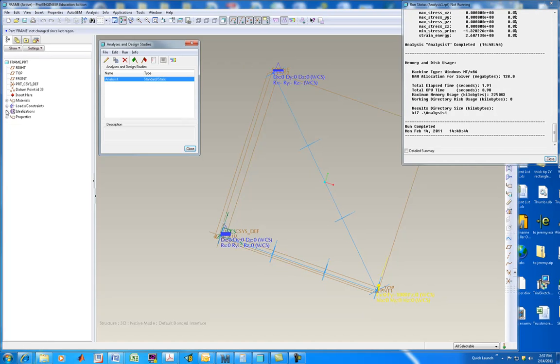I'm going to go over here to Idealizations, Beams, and let's click on the correct beam. And I can release it from either end, okay? Or I could release it on both, but it's unnecessary. If I were to say that the right-hand end of this bottom beam is not capable of transmitting moments through this joint, so I release the moment transfer in the z direction, then that should achieve my purpose. Or I could say that because I know this beam starts here and goes to there, the starting end of this beam also releases the moment. We'll just pick one of them.